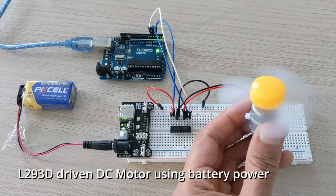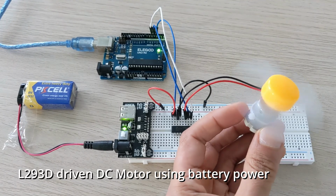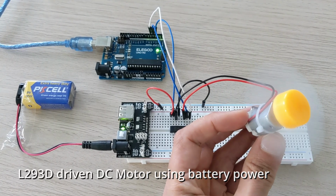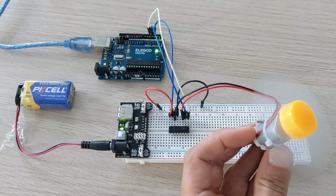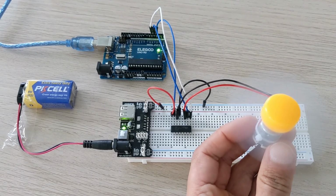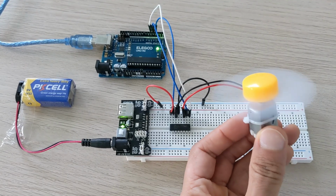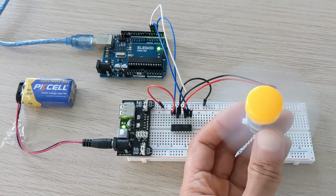Here we are using the L293D, which is a neat IC that packs inside everything one needs to drive inductive loads, such as relays, solenoids, DC, and bipolar stepping motors, along with the bidirectional drive and overcurrent and kickback protection, so no flyback diode is actually needed on our circuit construction.